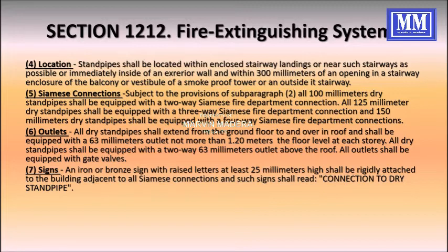An iron or bronze sign with raised letters at least 25 millimeters high shall be rigidly attached to the building adjacent to all Siamese connections, and such signs shall read "Connection to dry standpipe."